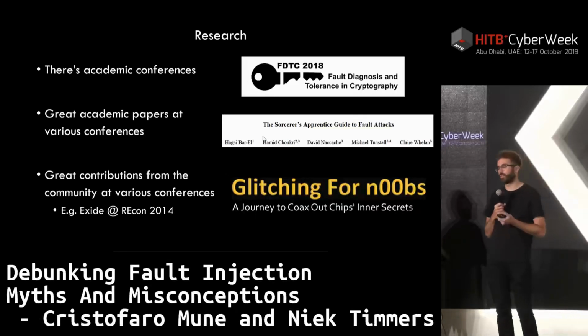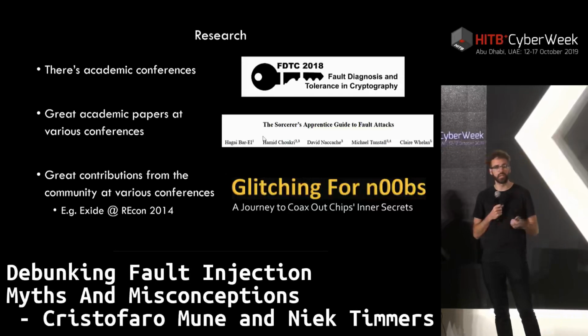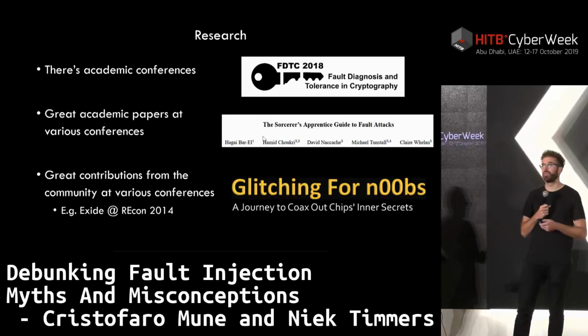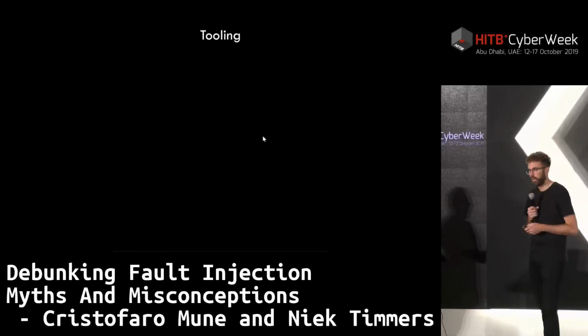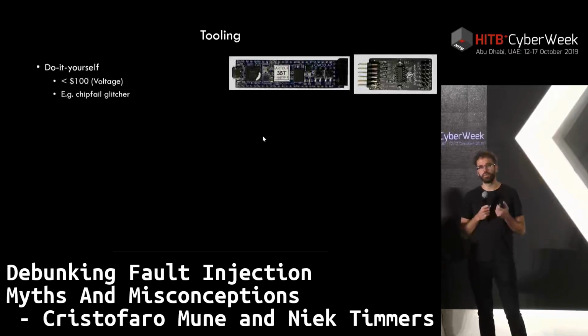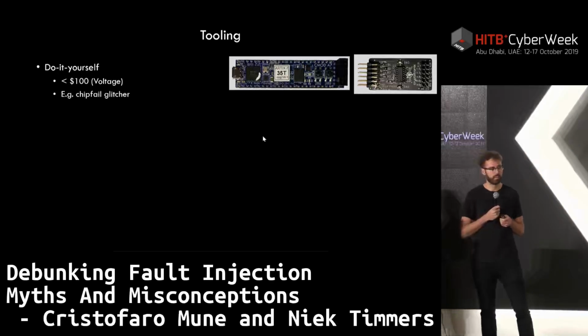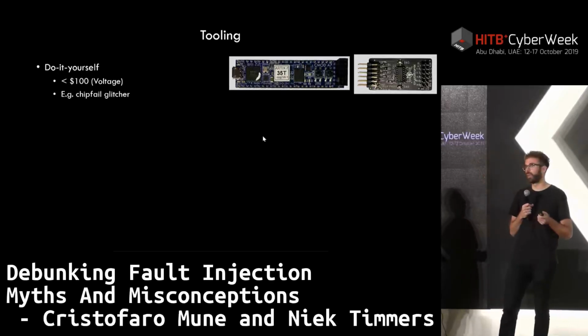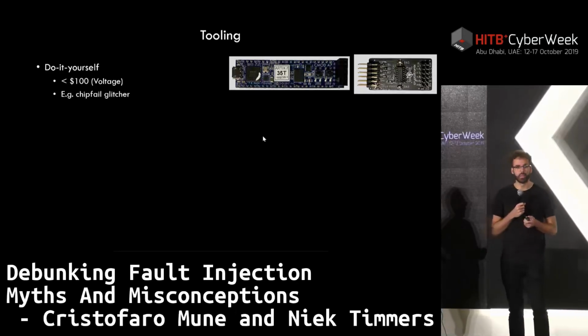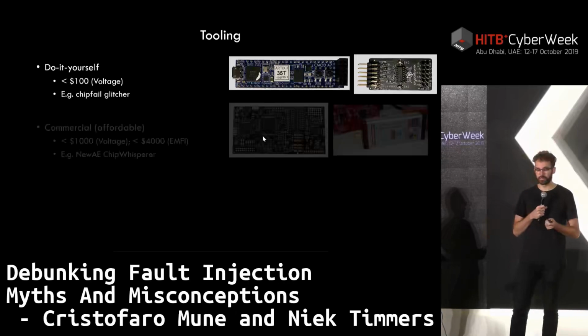For example, an early example was Glitching for Noobs by Excite at Recon 2014. But since then we've seen way more presentations about doing fault injection on a wide variety of devices. And the reason for this is because the tooling nowadays is a bit easier available than it used to be, for example, 10 years ago. Nowadays you can just go to GitHub and there will be various designs in order to make your own little glitcher in order to perform voltage glitching, for example. An example is the ChipFail glitcher, which was used recently in order to target various targets.